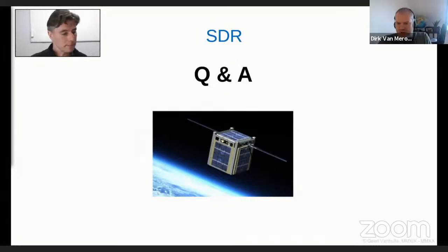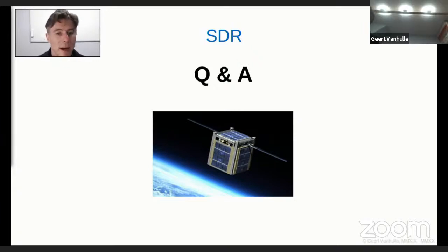Yes, I have a technical question here. How to take into account the delays in the circuits when doing digital signal filtering? Yes, so that's exactly why we need these high-speed CPUs. You've understood directly one of the problems that we have in software-defined radio: the delay in the whole flow graph. Of course, every processing step will add some delay, but we have this in analog circuits as well. This is often underestimated, but analog circuits also add delay. Of course, it's of another range, but it can be a problem there as well.